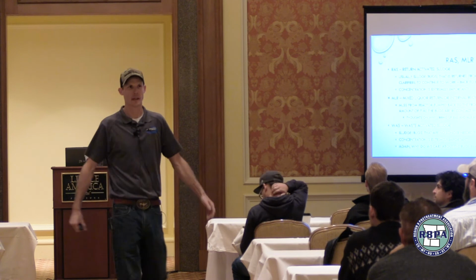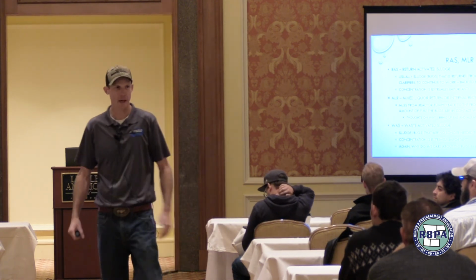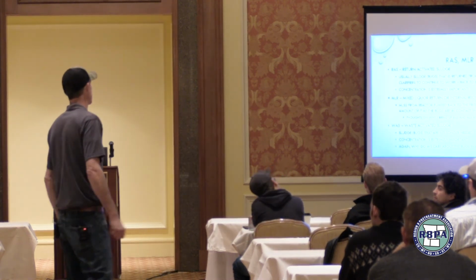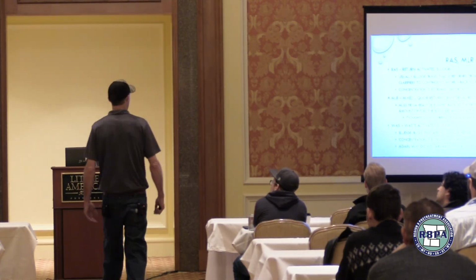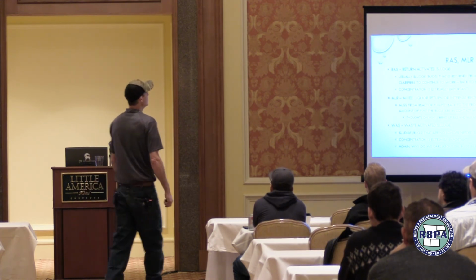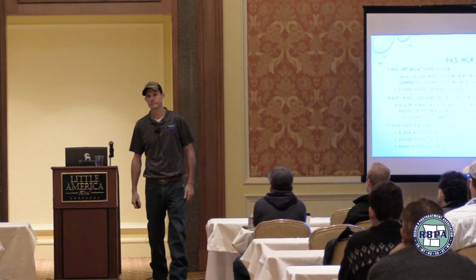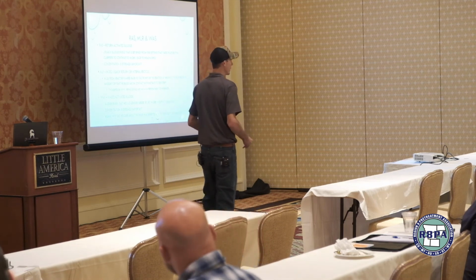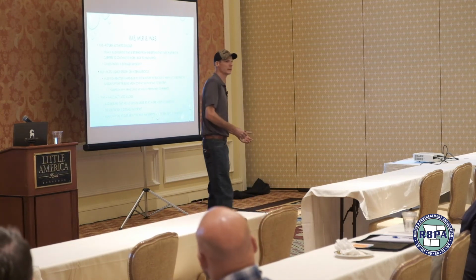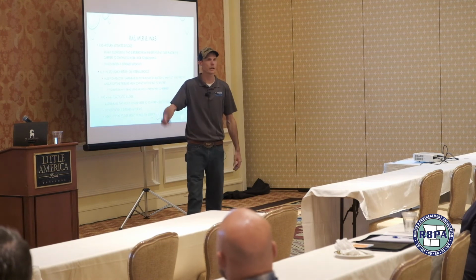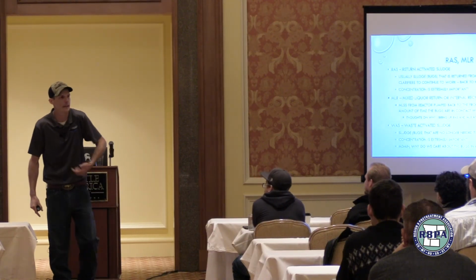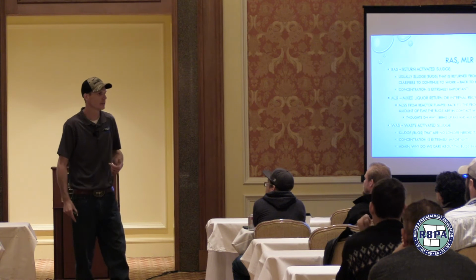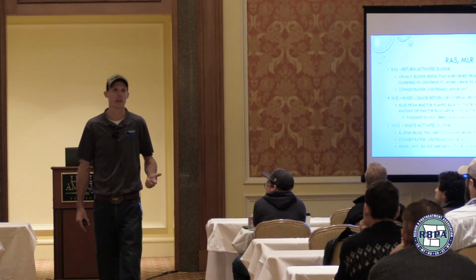Jessica knows for a fact that I'm not a fan because you're screwing with the biology. It works to some degree, but the mixed liquor return or internal recycle is literally a tool that an engineer came up with to not make you denitrify, to make the operator think less. Here's a pump, turn it on at 300% of your influent flow, and it will send the bugs back through your plant so many times that they will just have to be in contact with nitrate, and they'll denitrify. But what's that do? Costs money.